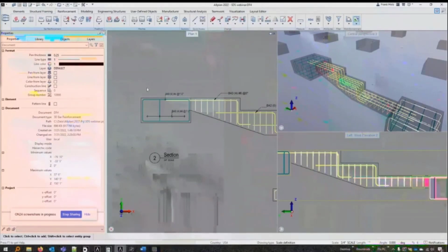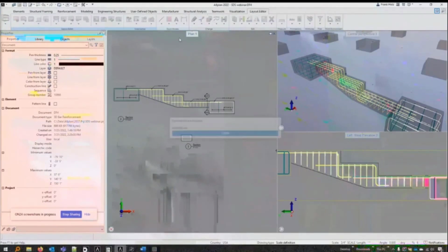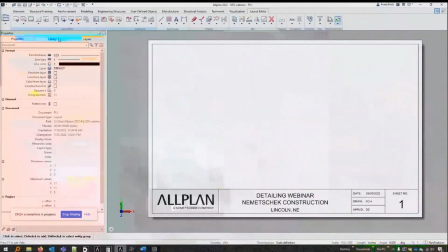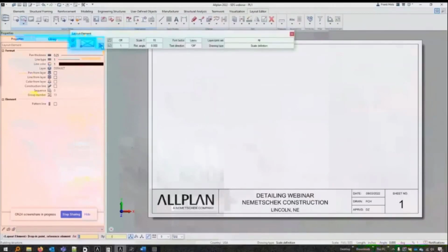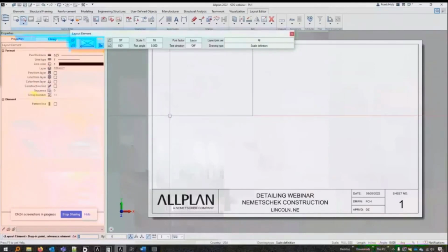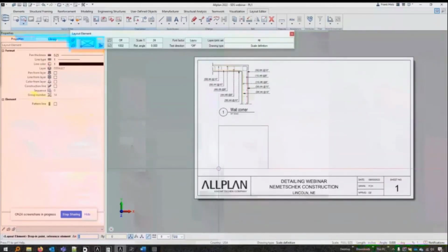All right, so now that we have a nice drawing and some nice schedules, we're going to go ahead and put these on a layout editor, or on a layout. And to do that in Allplan, it's exactly the same kind of workflow as AutoCAD. I'm basically going to select a viewport from my drawing. In Allplan, we actually have a little more functionality, where we create this nice derived from section over here. We can put them on their own little drawing files real quick, and it makes it real simple to plop down like that. You'll notice I get an outline for it.